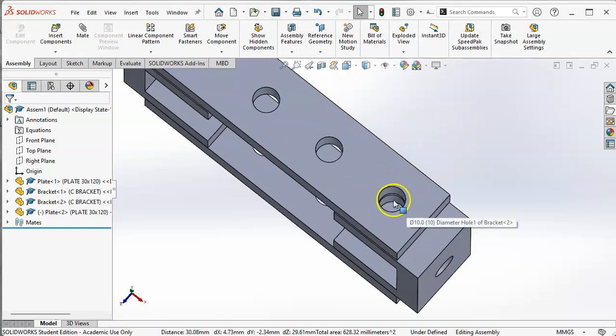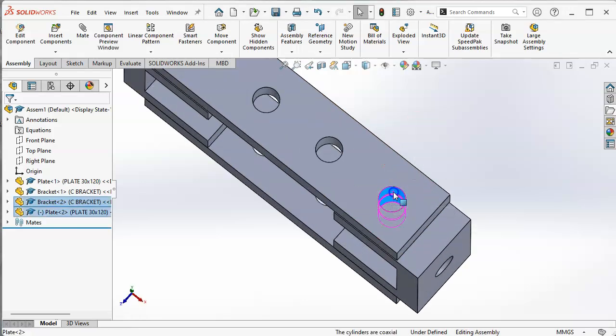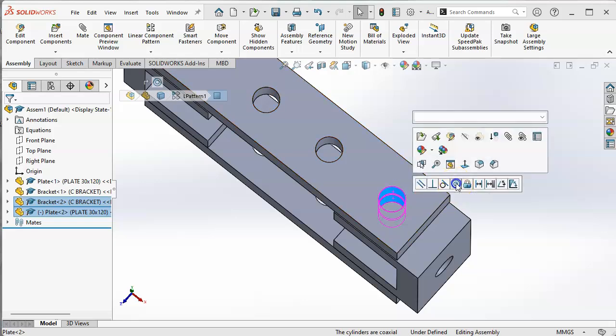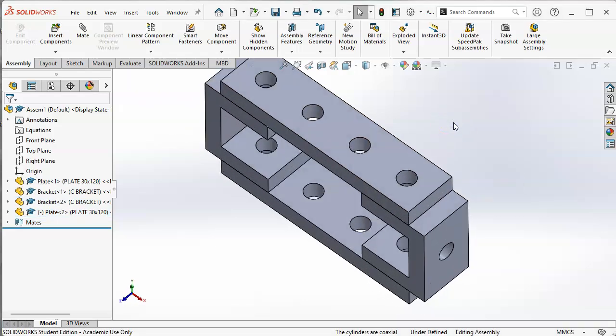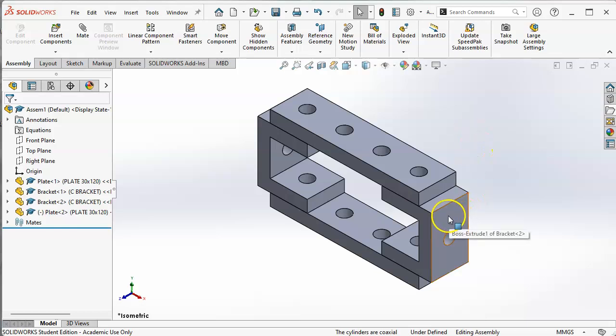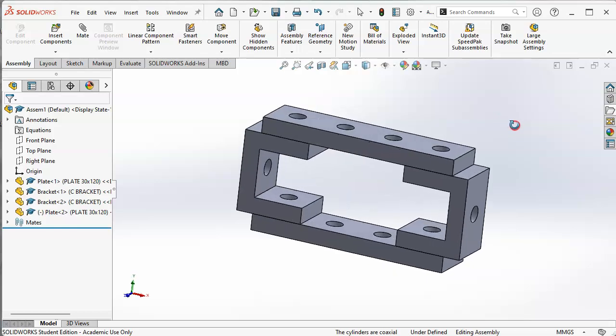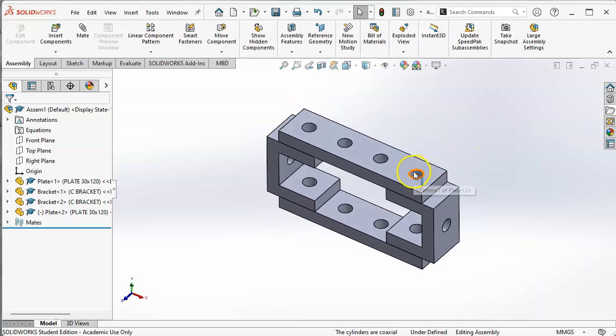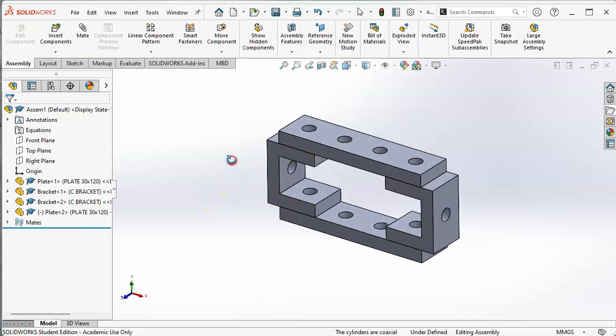What I do want is an error check, that if something happens to this whole position, that this geometry will change. So if we changed a dimension, if something were to be modified and not caught, then this would generate an error because it wouldn't remain concentric. All right, so we're going to bring in the peg.